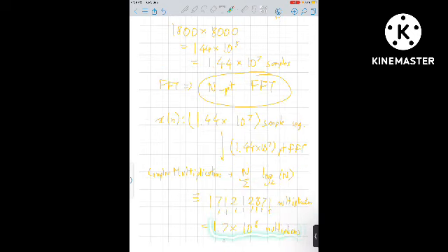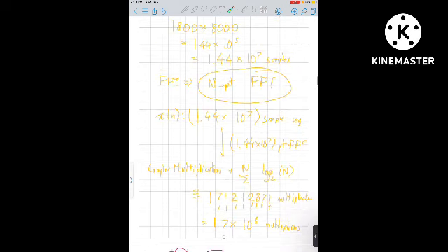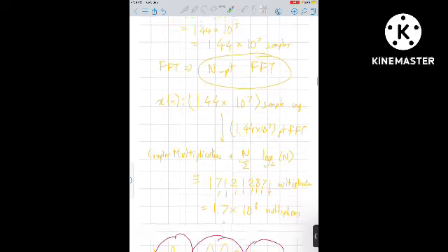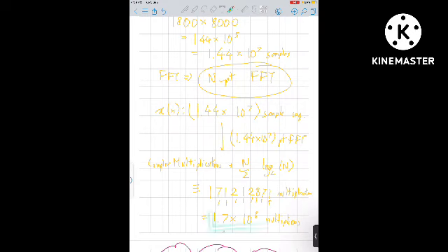Now imagine trying to have so many multipliers on your chip. What is the order? 1 2 3 4 5 6 7 8, so just less than a billion multipliers. We talk about a billion transistors on a chip, but your chip would have a billion multipliers. You can imagine how much area, how much power, how much delay would be involved in this. So it is really foolish.